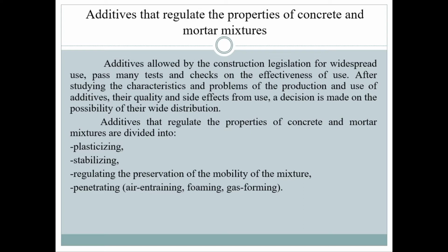Additives that regulate the properties of concrete and mortar mixtures are divided into plasticizing, stabilizing, regulating the preservation of the mobility of the mixture, penetrating, air entraining, foaming, and gas forming.